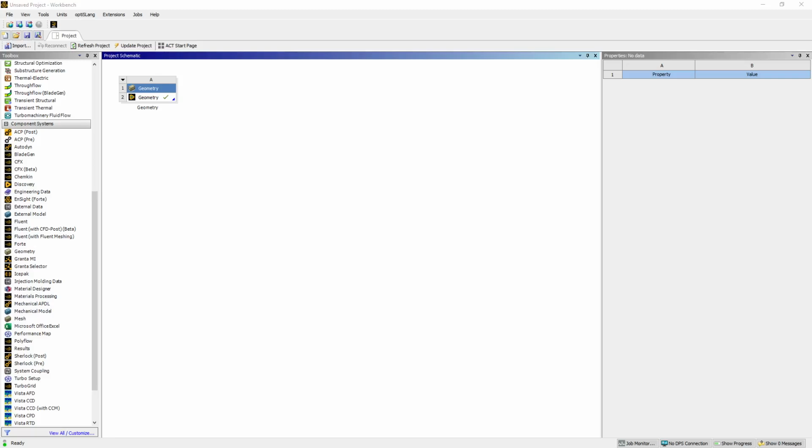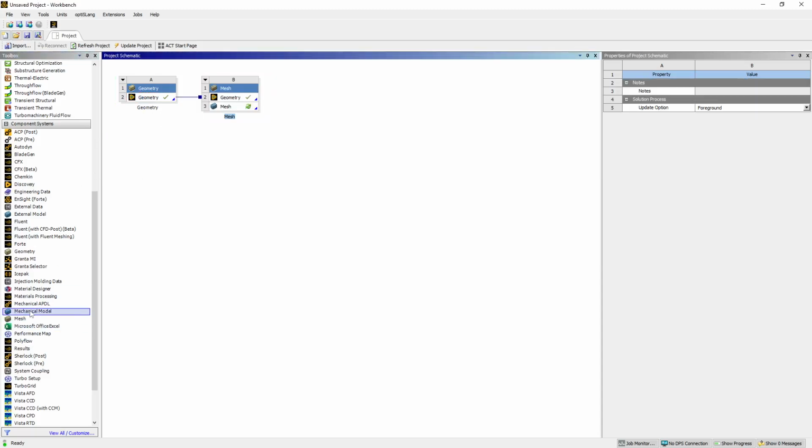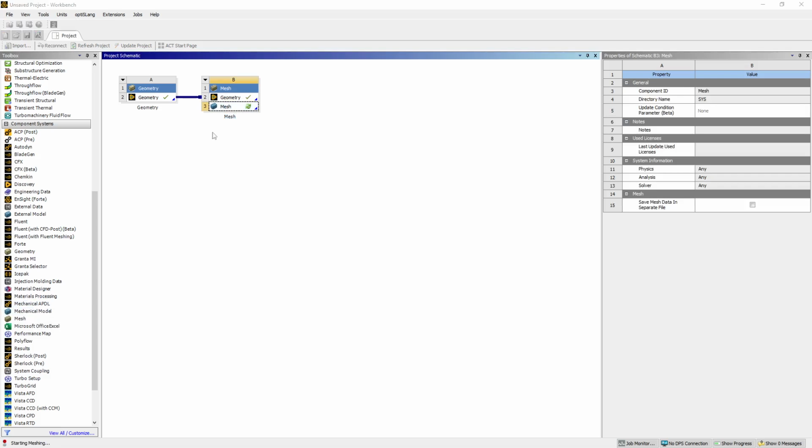In this video, we're going to mesh for CFD, so we'll use the mesh object. Structural meshes use mechanical, and we want to just open that geometry we finished editing in SpaceClaim and apply a few settings, then attach a Fluent model to that.